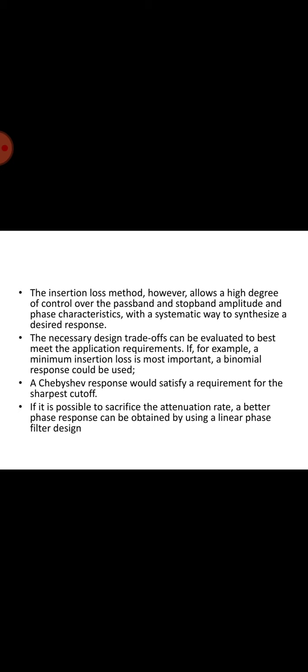If, for example, a minimum insertion loss is more important, a binomial response could be used. A Chebyshev response would satisfy a requirement for the sharpest cutoff. So, if it is possible to sacrifice the attenuation rate, a better phase response can be obtained by using a linear phase filter design.